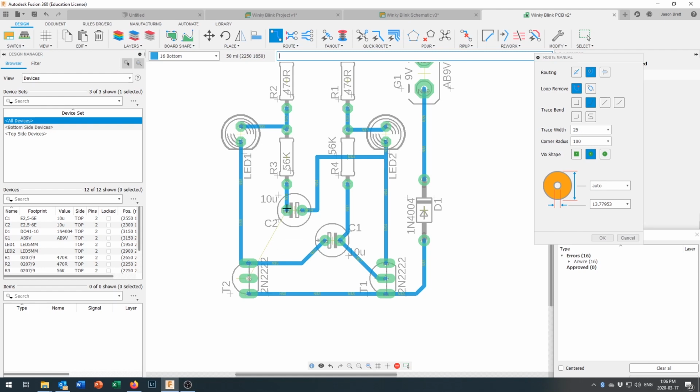Well, remember, it doesn't necessarily have to come from right here because this is connected right here, and we can go underneath other objects. If we could go underneath the capacitor, bit of a tight fit. If we could go underneath the LED, again, with the level of manufacturing we have in the high school shop, probably don't want to do that. But we can definitely go underneath a resistor and route it around this way.